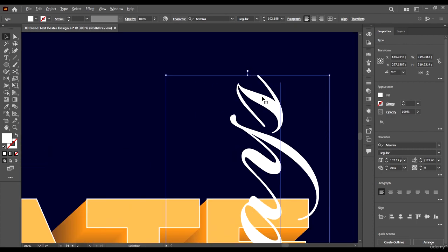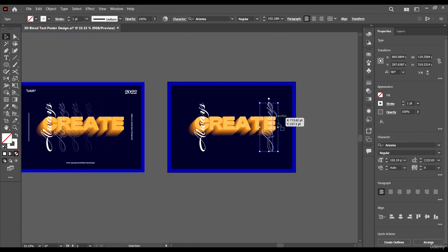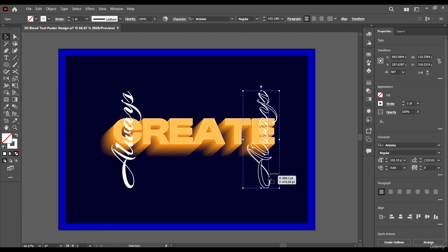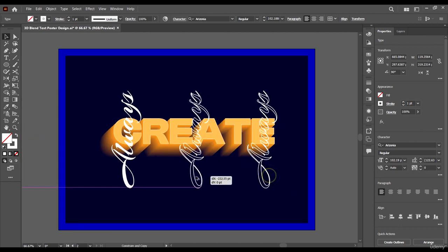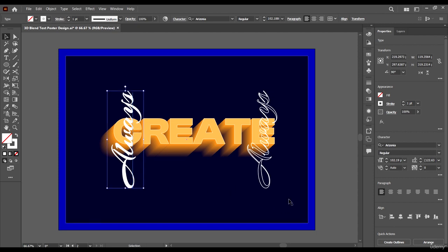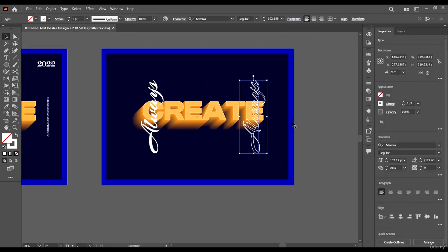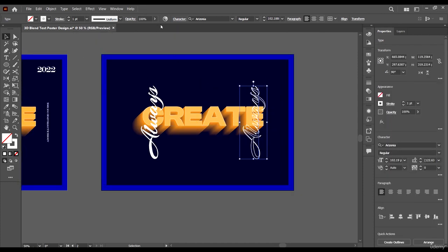And for this guy, I'm going to Shift X to give it a stroke instead, and we're going to then also hold down Alt to bring another version here. Okay, and now we're going to blend between the two versions. First of all we need to reduce the opacity of this guy. So take it to let's say 15. Okay, I think it's lower than 15.